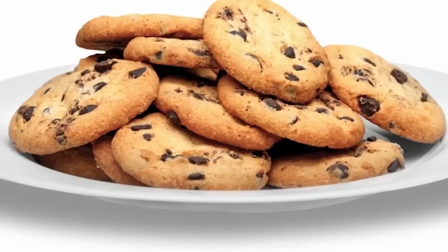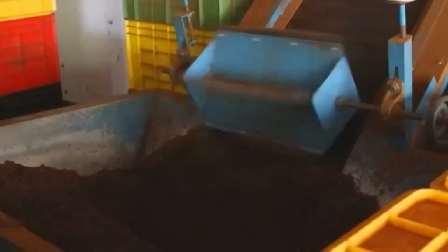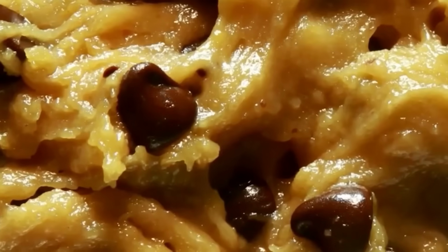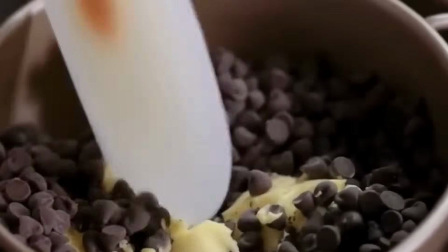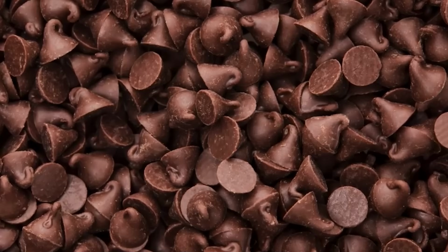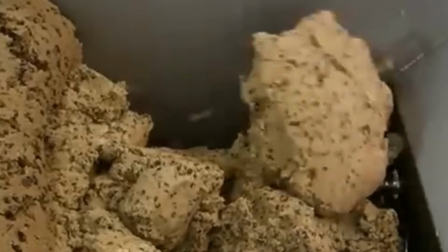Production lines are cleaned on a rotating schedule. Between batches, dry cleaning is performed using brushes and vacuum systems to remove flour dust and crumbs. At daily intervals, equipment is disassembled and sanitized using foaming alkaline cleaners, followed by water rinses and food-safe sanitizers. Chocolate lines undergo specialized cleaning to prevent fat bloom and cross-contamination. Allergen control zones are enforced through physical separation of lines, color-coded tools, and allergen-specific cleaning validations.